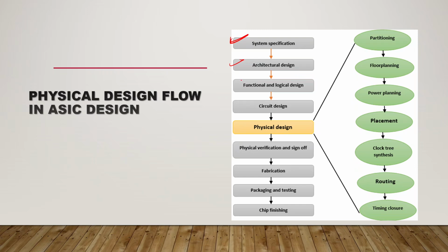Basically they will write the program in RTL. What is RTL? Register transfer level. They write the program in Verilog. Verilog is a hardware description language, HDL. I think you studied digital circuits; to describe that hardware we have a programming language, that is a hardware description language. These are the RTL designers, and they design this based on the specifications.